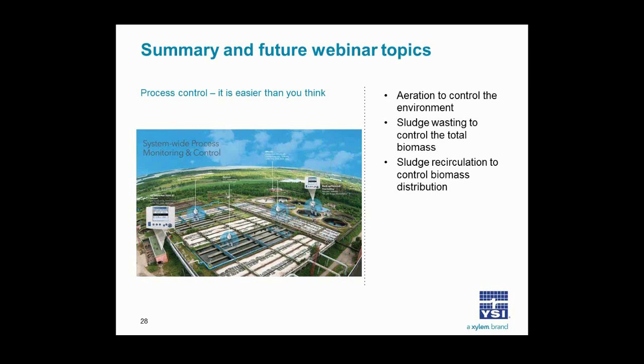This stays along that topic for phosphorus removal. Which measurements can be applied to phosphorus removal? Yeah, it's a good follow-on question. A number of utilities have used ORP very effectively, especially in batch-type processes. But the real gold standard would be orthophosphate measurement. The orthophosphate gives you an indication of phosphate release and also phosphate uptake.